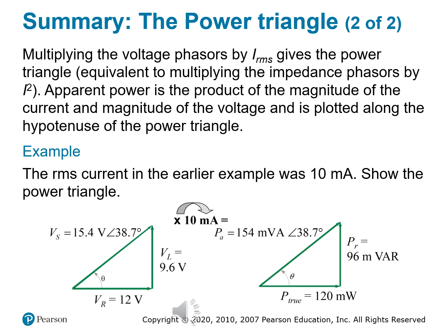So a power factor of 0.78, what does that mean? That just means that only 78% of your apparent power is being converted to useful work. So it's important for sizing power supplies, it helps you manage losses, and helps you tune for efficiency. If you learn this triangle and use it, it'll help you in your resistance and inductance journey, one that speaks not just of currents and voltages, but of what those waves are actually doing in terms of real energy.